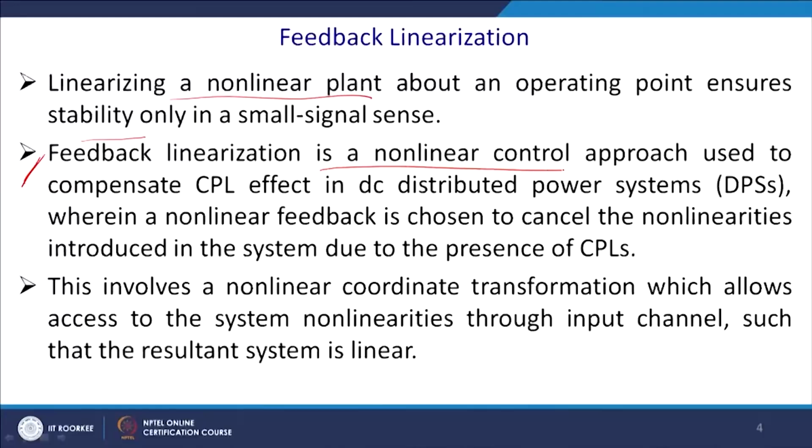And for this reason we need to go for nonlinear control, where feedback linearization is a nonlinear control approach. We take the feedback and linearize it, to compensate the constant power load effect, that is the CPL. I told you this is one of the very nasty entities in our DC microgrid.